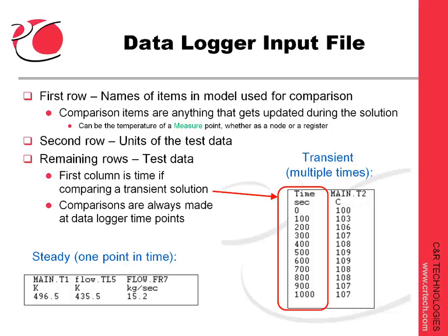When using the comparison method, though, the results will be combined into a single object for each time through the evaluation procedure. You should also note that these tables don't have to be test data. They could also be predictions made by a more detailed analysis, including a CFD code, but maybe even a more detailed TD SINDA model. In other words, you can perform model correlation to help generate a simplified model from a more complex one.